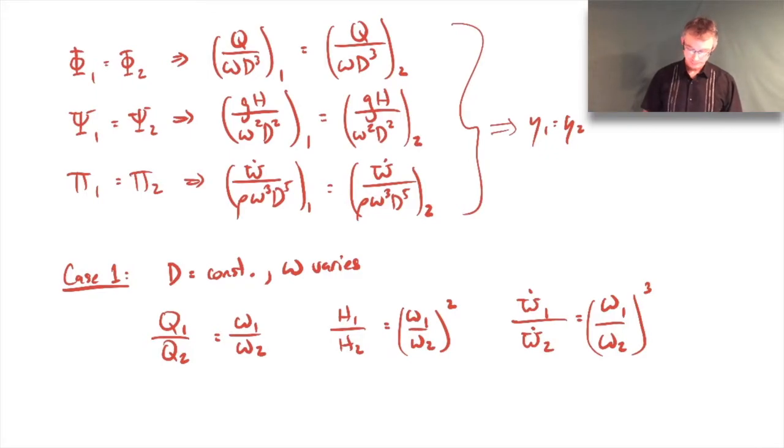And then, again, the efficiencies will be more or less constant in that particular case. So that's how you would do scaling when you're dealing with changes in rotational speed. It's fairly straightforward. You would know from your manufacturer what the pump performance curve is for a particular rotation speed.